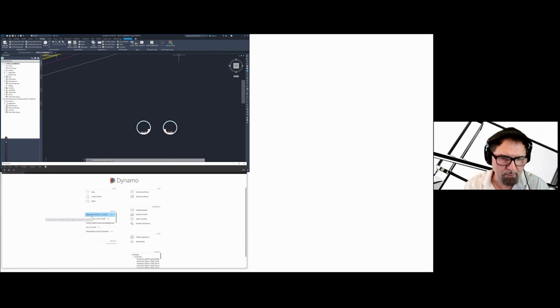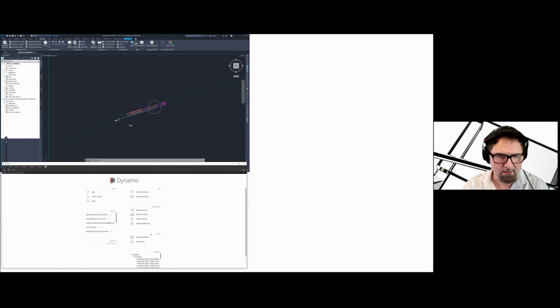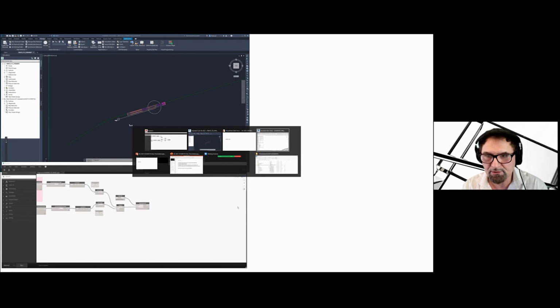Open that Dynamo. That will basically collect some data from the drawing and send that over to Civil 3D. Of course, we have to open the Dynamo in the host drawing file, so we're going to do that. And running this script can be manual or automatic. It's probably better to not have it automatic. I'm going to go now to Revit and do the same.